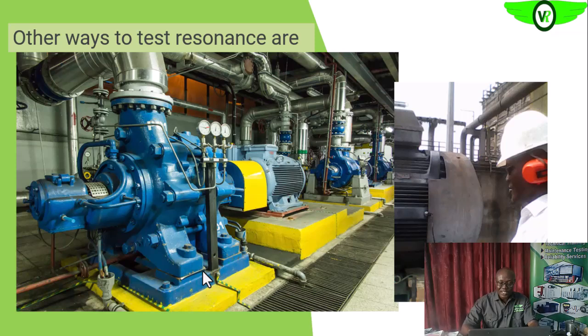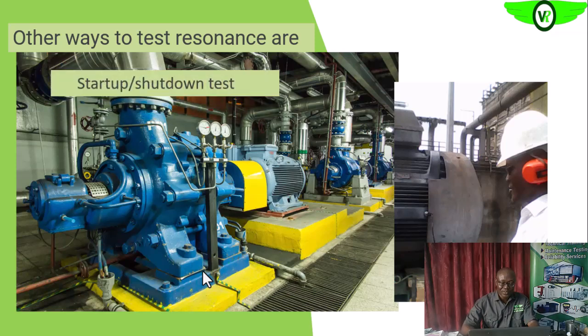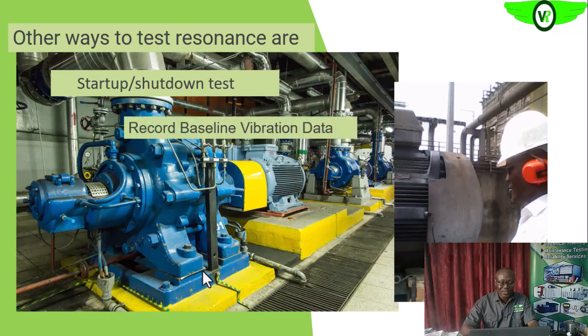Resonance is not something that you just confirm straight from a single piece of vibration information. Once you suspect resonance, you have to test further to confirm that what you're actually having is a resonance condition. So we have the startup or shutdown test that you can carry out.